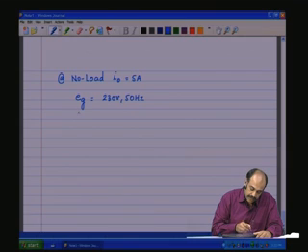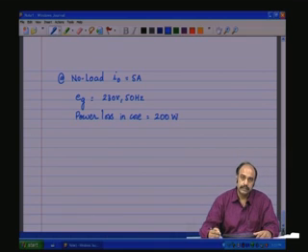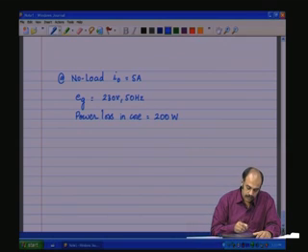And from the wattmeter test, that is by connecting wattmeters, the active power, that is the iron loss or the core loss, the power loss component in the core, is 200 watts, let us say. Now, if this information is given, let us find out what is the apparent power.